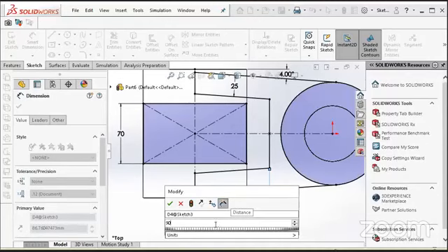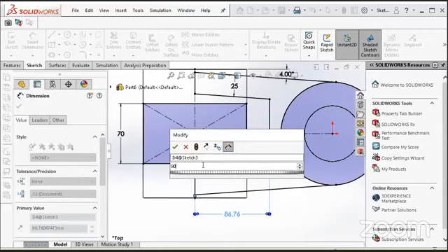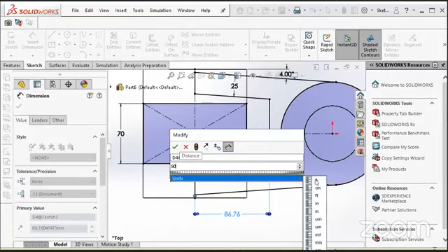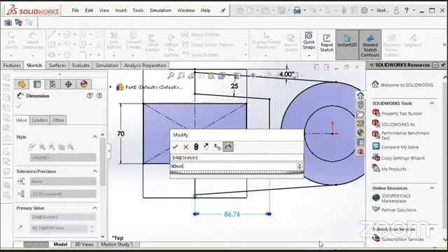As you can see, I am still working in millimeters, but I want some dimensions to be selected in centimeters and automatically converted by the software into millimeters. For that, I will define my numbers, and here in the units I can select centimeters, feet, or inches. If I consider inches, it will convert 90 inches into millimeters. But in this case, I will make this one 90 millimeters and click okay.